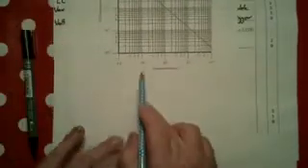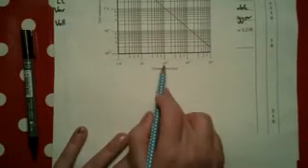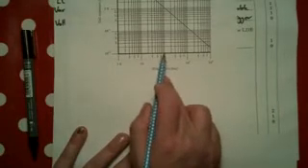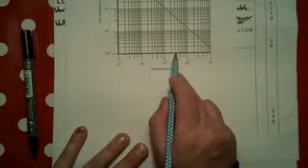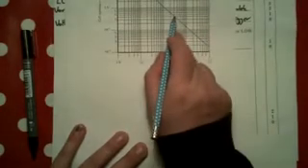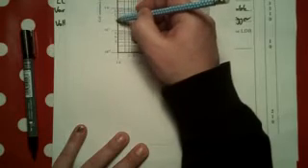Okay, what's next? It says determine with reference to the data booklet the resistance of the LDR. I've got the page here, and so what we need to do is find the light intensity of 300 lux. Well, if you look across the bottom, you've got 10 lux and you've got 100 lux. 10 to the power of 2 is 100. We're looking for 300, so that would be 200 and 300. We then go up to the line, and where it intersects with the line, go horizontally, and we get to here. Okay, so we can now see that this would be 1 kilo ohm, so that would be 700, 500, 400, 300, so it's 400 ohms.